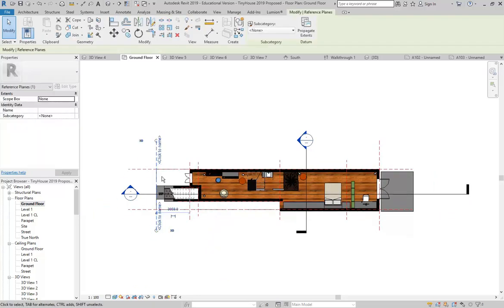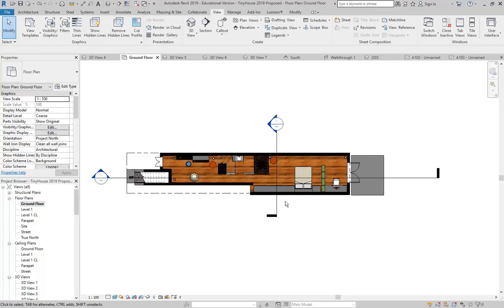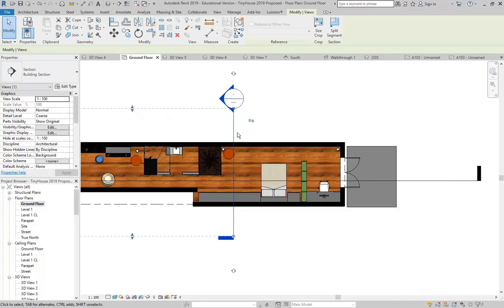And then the reference planes, VH. So I have the category. No, just VH, yep, no enter. Yeah, AutoCAD you've got the enter, but with Revit shortcuts usually you don't. So now I can just adjust the sections a bit more because they're bigger than they need to be.